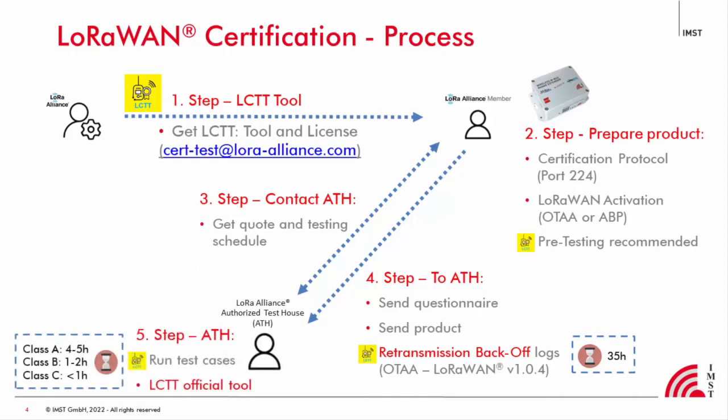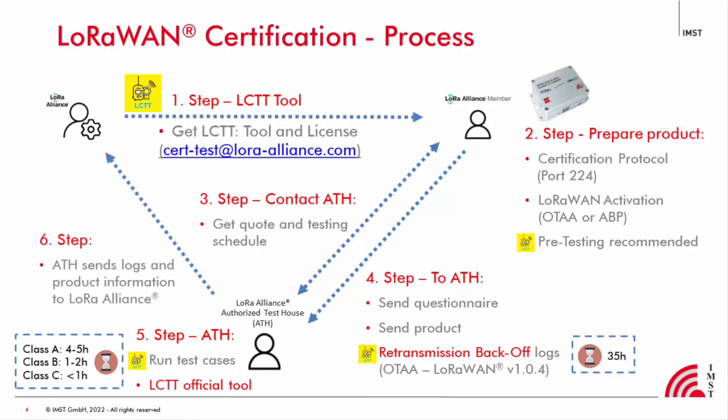The test house will run the test in an anechoic chamber using the LCTT as official testing tool, and it will share with you and with the LoRa Alliance the successful results. Finally, you will get your certificate within few days.